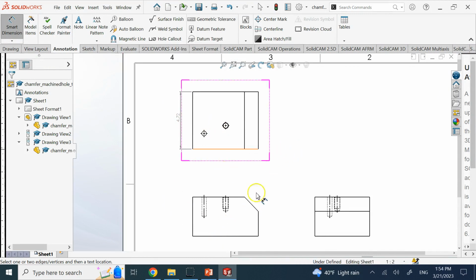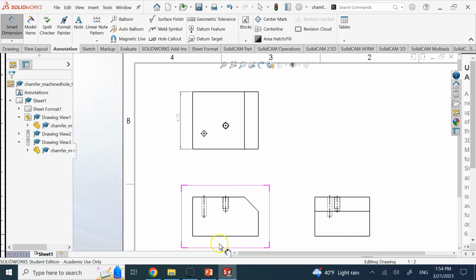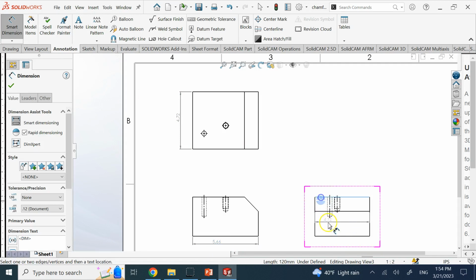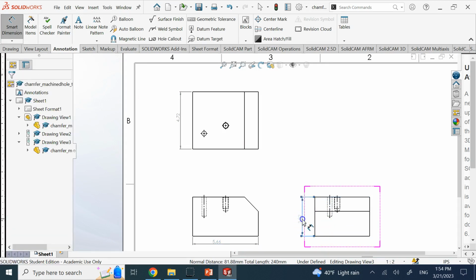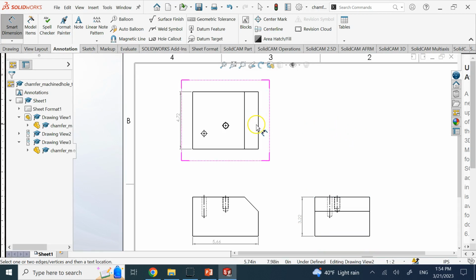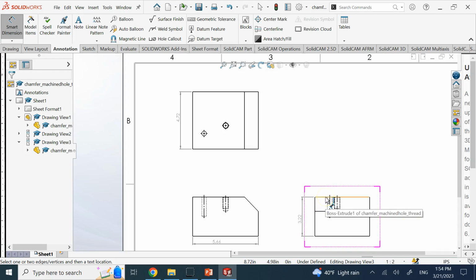And you might say, well, I have three views, and so I'm going to add the depth to this view, I'm going to add the length to this view, and I'm going to add the height to this other view. Well, this is not typically a good idea when you're doing what? Drafting. Because most of the time, out of your three views, you can say always, but in simple cases, definitely, one of the views is redundant.